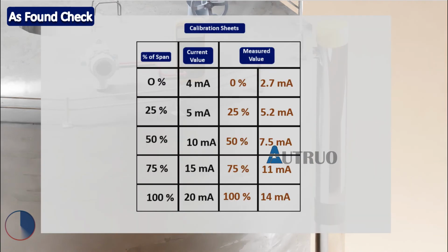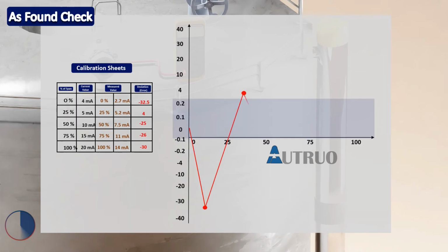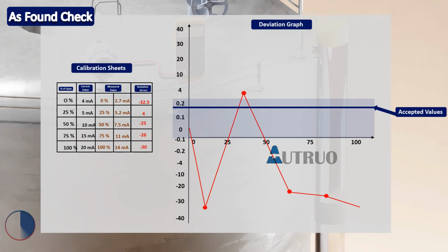These values are not acceptable, because when we compare the value gotten with the transmitter data sheet, we can see that it is far off from what is expected. The graph shows a lot of hysteresis, and as such the deviation between the two graphs is more than 0.2%. 0.2% deviation is the accepted tolerance value in some states, and it is the reason why the tank overfills in the first place. Hence, there is need for recalibrating this instrument.